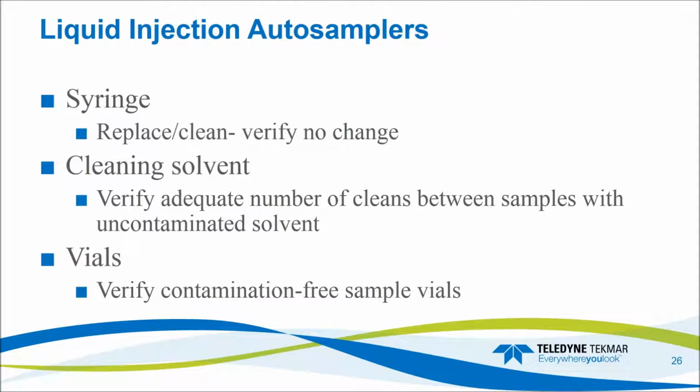So if the issue is coming from our liquid injection autosampler, we really have three main sources that could be contaminated. It could be our syringe, in which case you'd want to replace the syringe or clean it, rerun, and verify whether or not you see improvement.